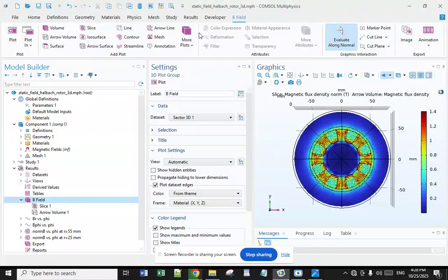And flexible, not hard ceramic, ferrite refrigerator magnets are created with a Halbach magnetization pattern for a stronger holding force when attached to a flat ferromagnetic surface, for example, a fridge door, than the holding force from a uniform magnetization. They are made from powdered ferrite mixed in a flexible binder, for example, plastic or rubber, that is exposed to a Halbach magnetization field pattern as it is extruded, permanently giving the ferrite particles in the magnetic compound this one-sided flux distribution, which can be viewed with magnetic viewing film.